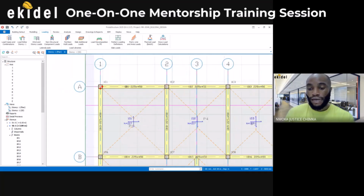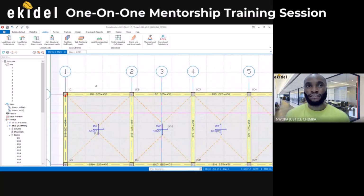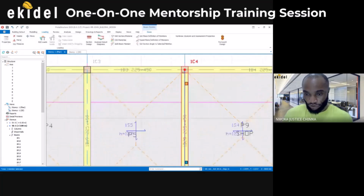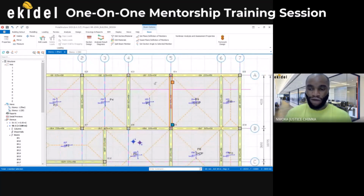So again, I'll do the same for all the ends. Just to be fast with it, once you have known your I end and your J end very well, I can choose to do all at once by holding my control key on my keyboard and then selecting all the ends that are J first. This beam here will be hinged at J, right? So I'll click on it and hold my control key, and then select all the beams that will be hinged at J end, which is the right.